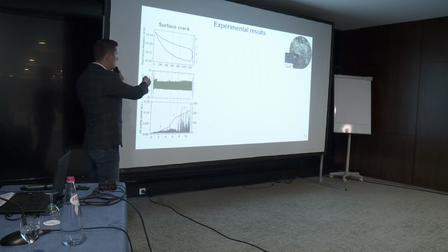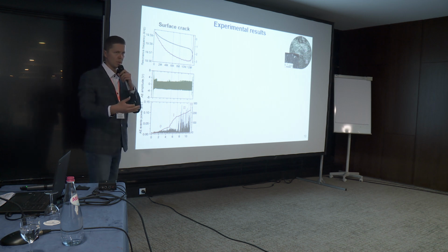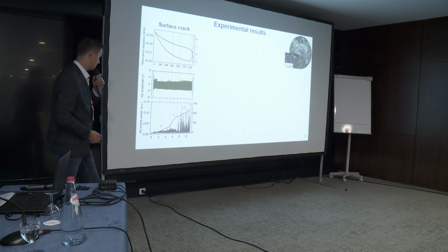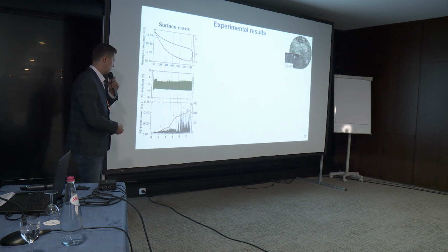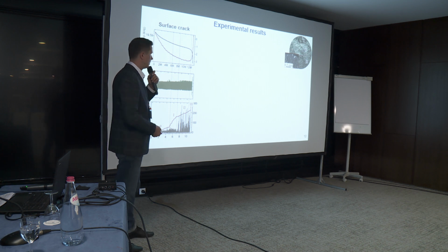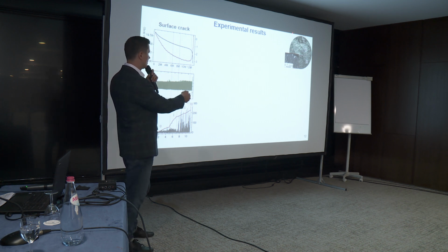We don't see any particular zones or knees on our curves. However, if we look at the acoustic emission events power distribution, it has distinct steps, and the number of steps coincides with the zones of fatigue fracture, which you could see.